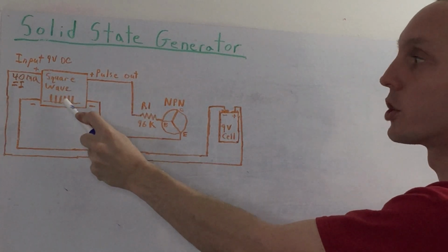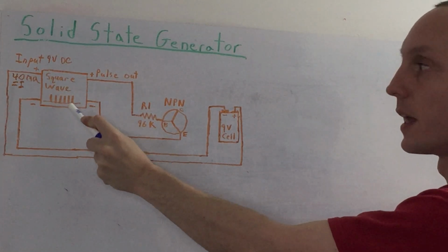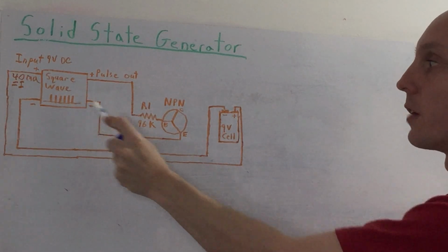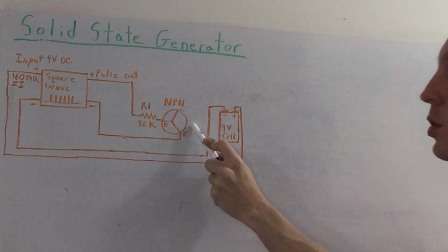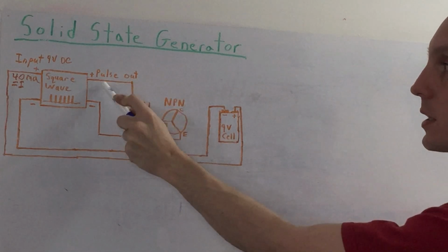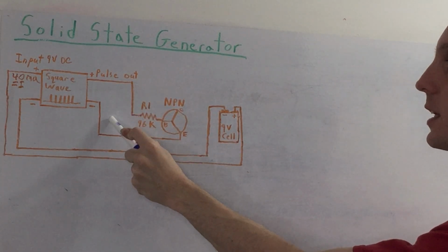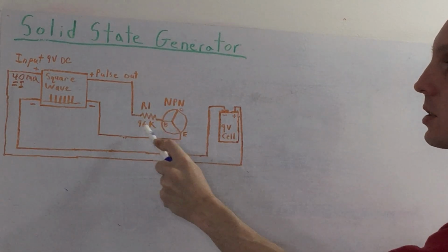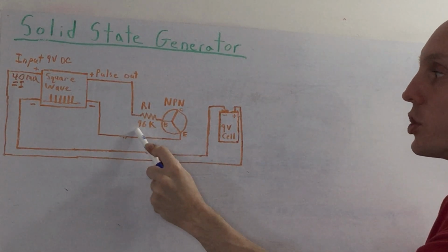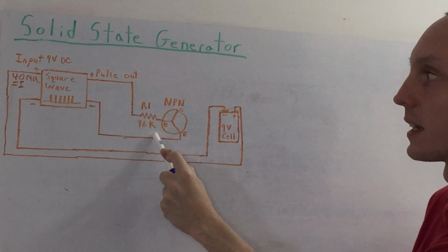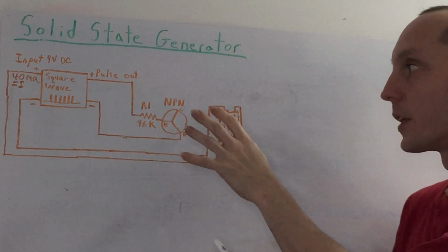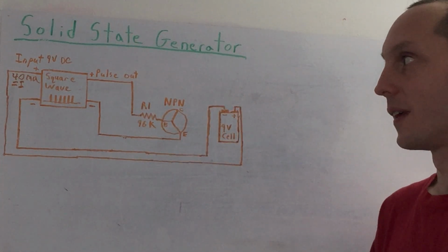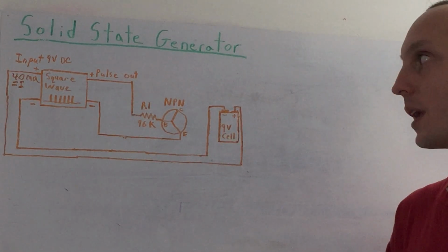I want a really sharp pulse, so a 1 or 2% duty cycle on the square wave, just to pulse an NPN transistor here. So this is the pulse output here, which is a typical setup for an NPN. R1 is the base resistor. Don't hold your breath on it. I just guessed this, 96K. You see, transistors, folks, this is why I hate them.